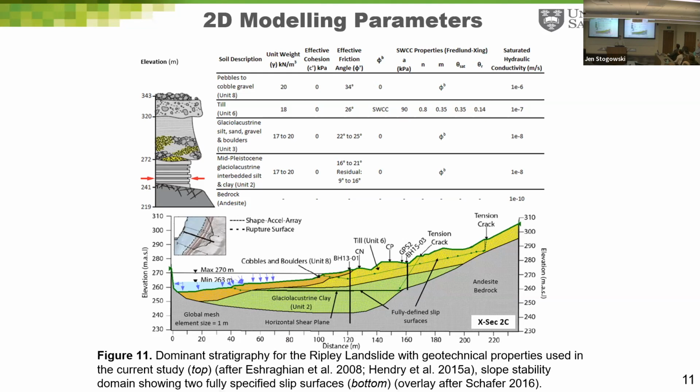Geotechnical parameters came from previous studies, and focus was placed on the unsaturated strength contribution from the superficial till found in the upper reaches. All other units were assumed to have no unsaturated strength component because they were composed of coarse grained material, were non-existent in these cross sections, or were present well below the ground surface, and conditions were expected to remain saturated there.